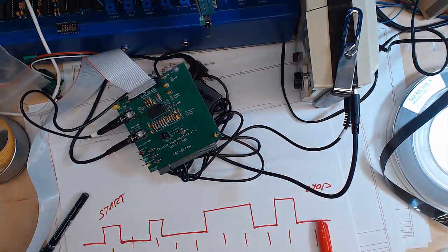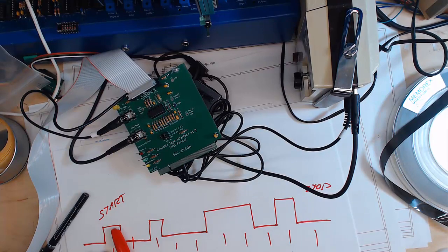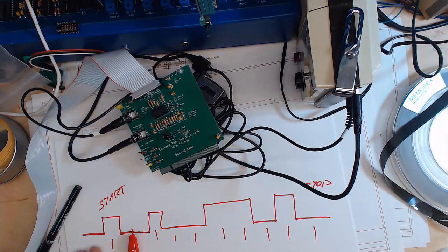So this is a serial data stream, and let's say that this could be something like RS-232. Say that the line is normally low. We'll have a start bit, and then we'll have some data, and this is our data all the way through here, and we have a stop bit. And the way we convert this back to data is we have to come through, we see the start bit, and we count a timer. So we time for a little bit, and we take a sample of the data, and it's either low or high. We time for a little bit, take a sample of the data. In this case, it's high. Time for a bit, low, time for a bit, low, high, high, low, high, and then we are done with that byte, and so we would have our stop bit down here.